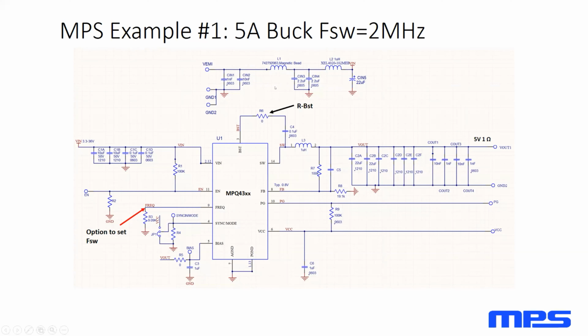If you have, let's say, on our 5-volt circuit, 6.3-volt rated parts, you may only get a third of this 22 microfarad value, and that's impacting both the ripple on the output as well as potentially EMC. That could very well affect over here, right? That's going to change the frequency at which these guys are effective.